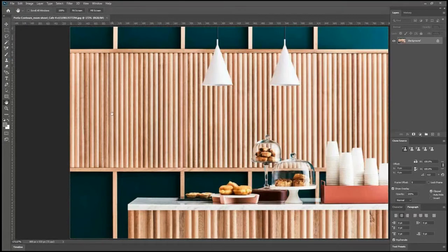So here's a Photoshop file of the material. And if you take this photograph here and make a material out of it, you can apply that material to your wall. And instead of having geometry, which again slows down the user experience in Revit, you have a photograph that you can paint onto a wall. And that is what appears in your rendering. Now, there's a little bit more work you have to do because it's more of a custom pattern. So you might need Photoshop.